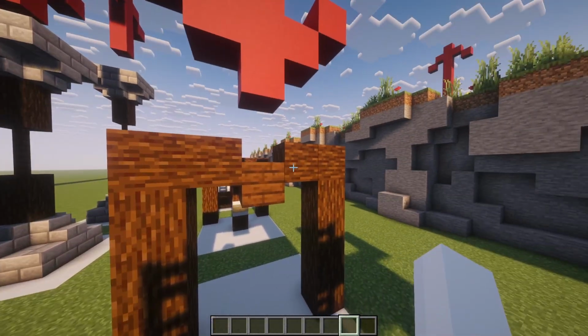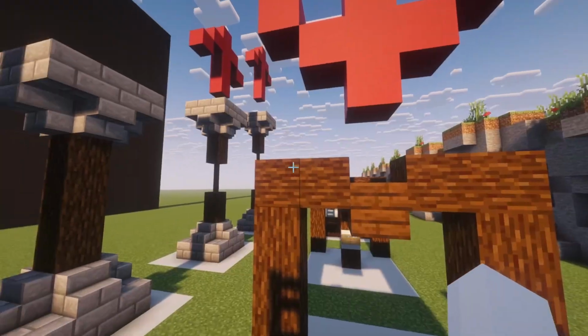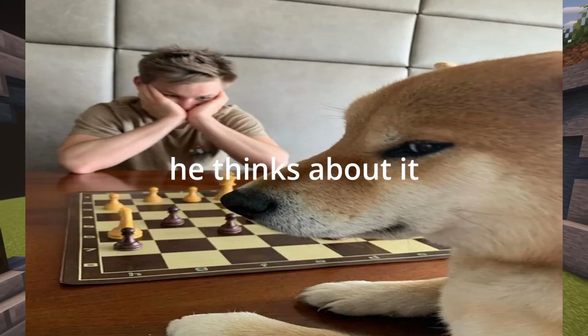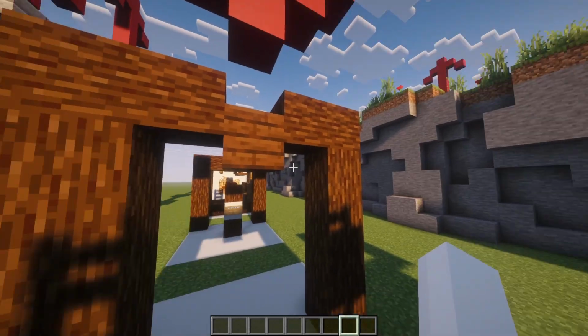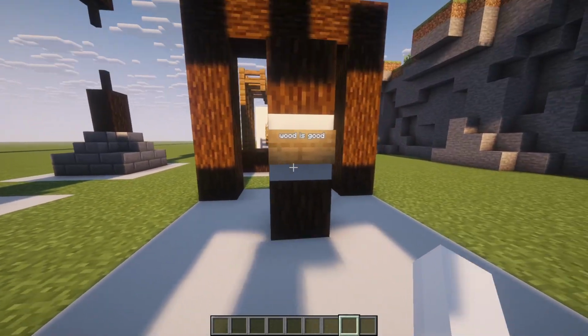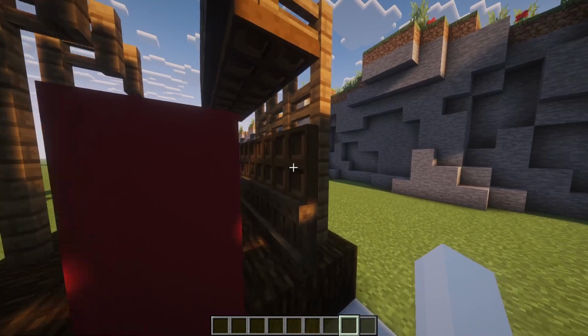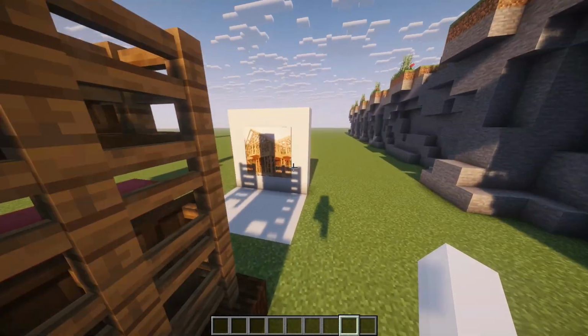Now, when we actually move on to a beam that's between two columns, the beam tends to bend in the middle. Here in this case, it would be compression at the top and tension at the bottom. Think about it, right? Pushing this in, these are being pulled out. But here's the thing, wood is actually really good. You can just make beams and columns out of wood, and you can place walls on those beams and columns, and you have a pretty good solid structure.